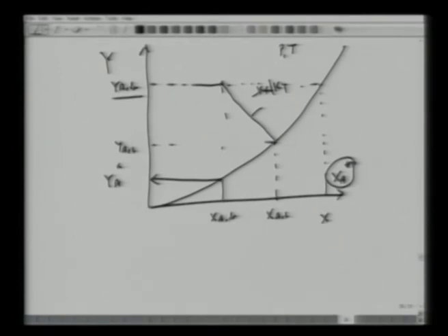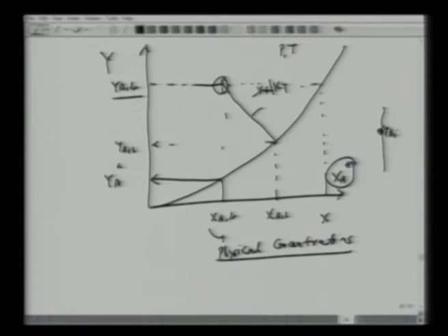But it's very important to note that in reality we have one yab, xab. These are the two physical or measurable concentrations. xai and yai are also physical. They also exist at the interface, except we are trying to avoid the measurement of these concentrations, yai and xai. Xa star and ya star, these two are hypothetical. They do not exist in the system.